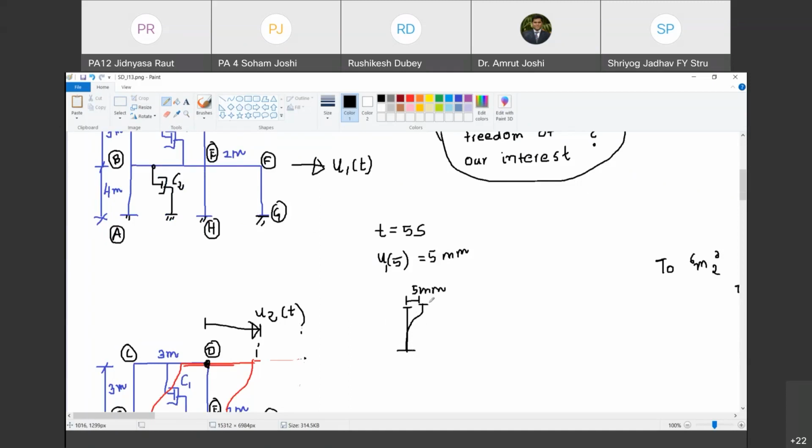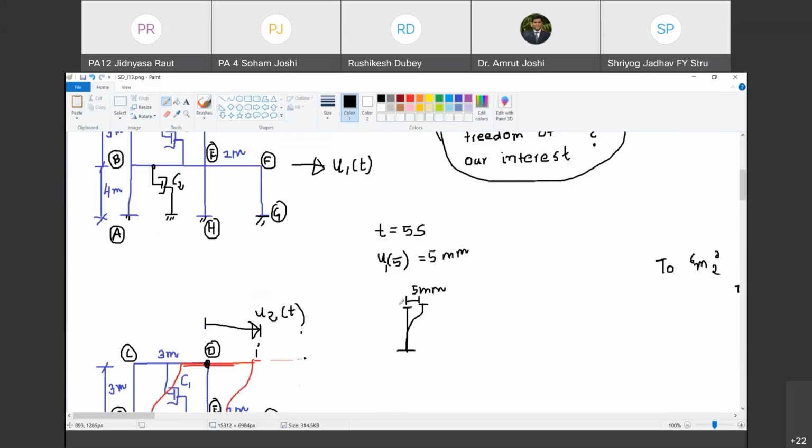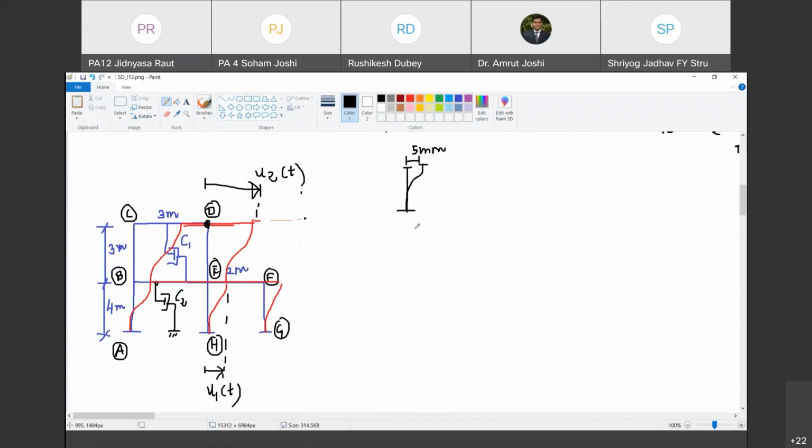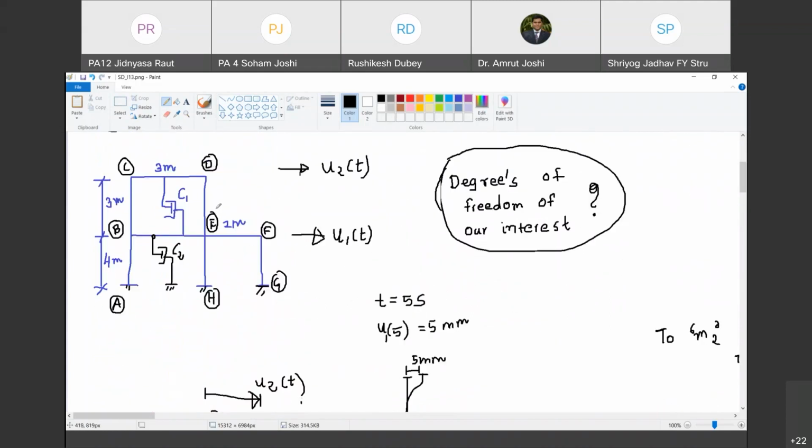It is going to induce bending moment. It is going to produce a bending moment diagram for column FG, and bending moment in turn is going to induce various bending stresses in this column. Do you agree with me? Yes, sir. And we are talking about bending stresses, not the stresses due to gravity load. So forget about gravity load now. We are talking only about the bending stresses induced due to these lateral deformations. Happy? Yes, sir. Okay.